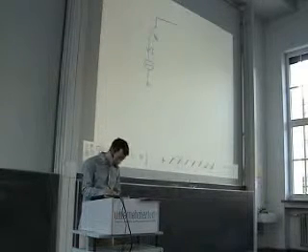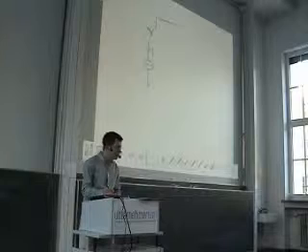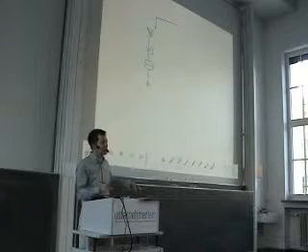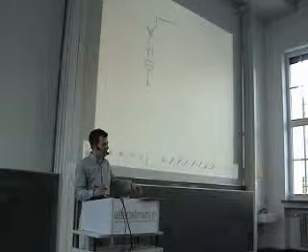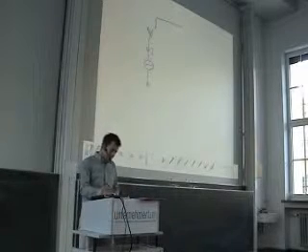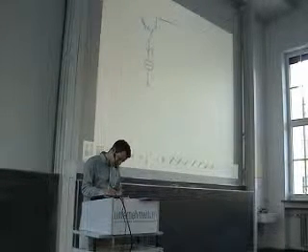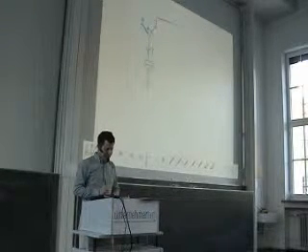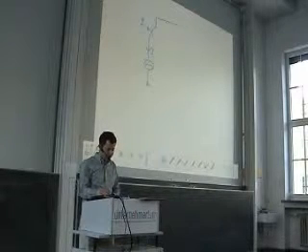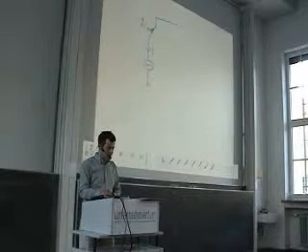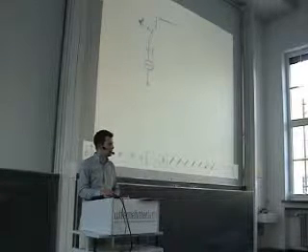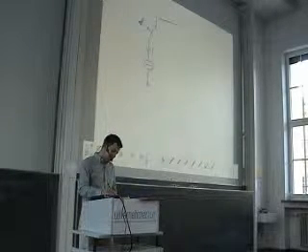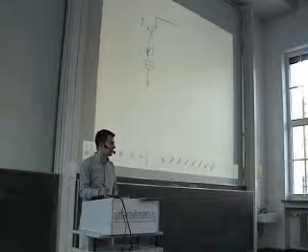Well, if I would disconnect it here, the current source still wants to sink this current. If it is connected to nothing, then in the ideal case we have an unallowed situation. So we can connect it here also to an analog ground. Then the current source always sees the same potential. Here it sees the virtual ground. Here it sees the analog ground. From a potential perspective, this is the same. So it can, in both situations, sink the same current.